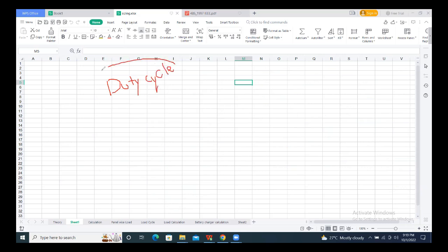This totally depends upon the way you are predicting the stages the battery may come into. You have to get the data from the O&M teams. If you are constructing a substation, or already have a substation that has been running for the last decades, take the information from the team: at what time, at what loads, loads were added on the battery at periodic times. Then you will get to know that the battery is failing in these cases, and what loads can be expected at that time.